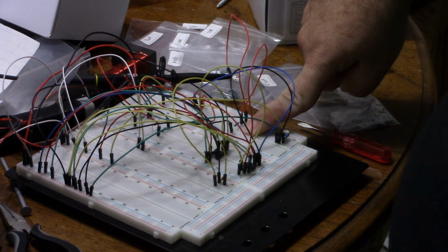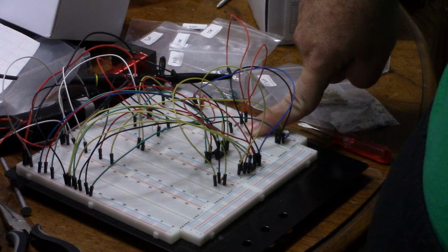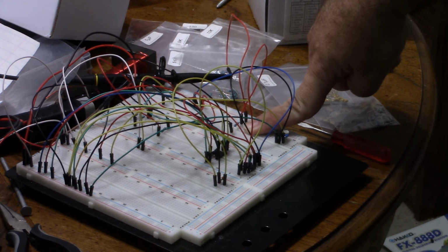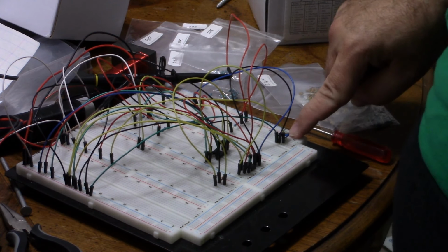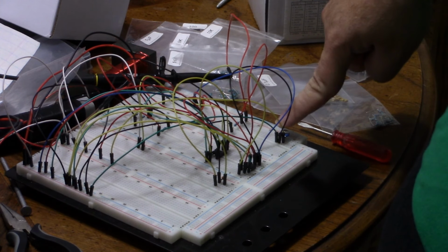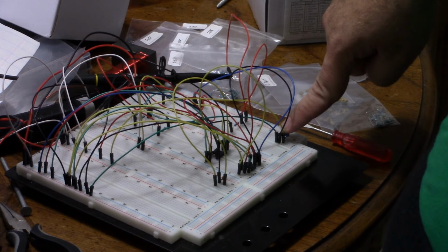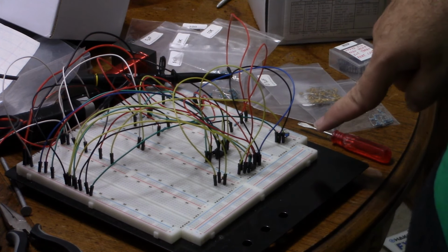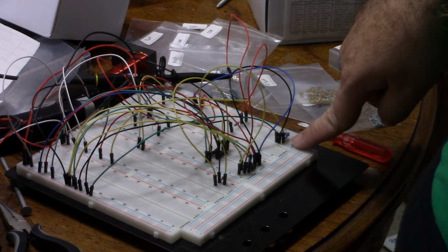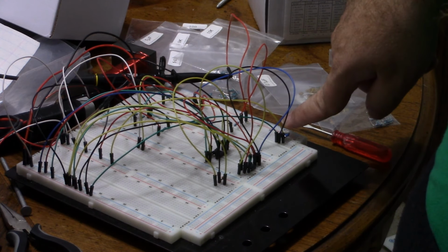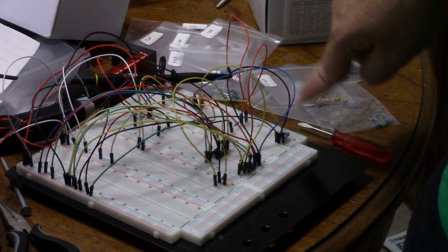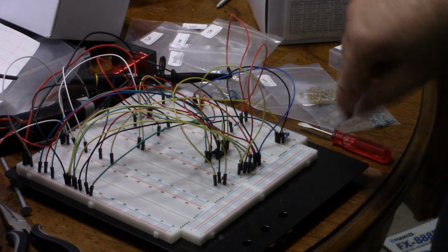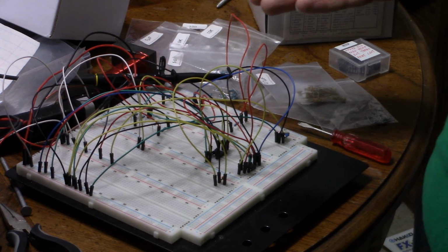That mysterious VCC to output parallel resistor that I need for my chip is a 10K. The datasheet uses 1K, but I use a 10K. And I have a potentiometer set up. This is a trim pot, but it's a potentiometer set up as a voltage divider so that I can control the control voltage. The size of the potentiometer doesn't matter except for how much waste current and waste power you have, because it's a voltage divider, so it's just percentage based. And that's the whole setup. So let's take a look.